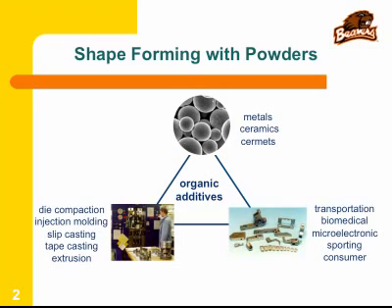And also how, depending upon the concentration and molecular weight of the polymer, that changes the properties of the solution in terms of the flow properties, the rheology. And then once you add powders, how the flow properties change, because you need to create a shape. So slip casting and tape casting is with solutions of polymers. Injection molding and extrusion is with polymer melts. And die compaction is an example where the additives are used in the solid form without any liquid phase present. Right?